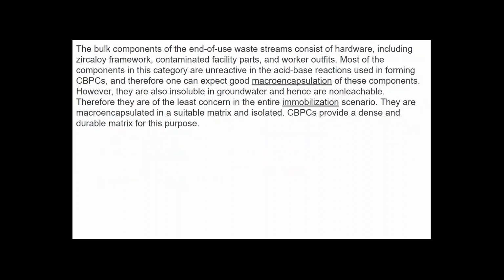And the bulk components of the end-use waste streams consist of hardware, including zircaloy framework, contaminated facility parts, and worker outfits. Most components in this category are unreactive in the acid-base reactions used in forming CBPCs, and therefore one can expect good macro-encapsulation of these components.